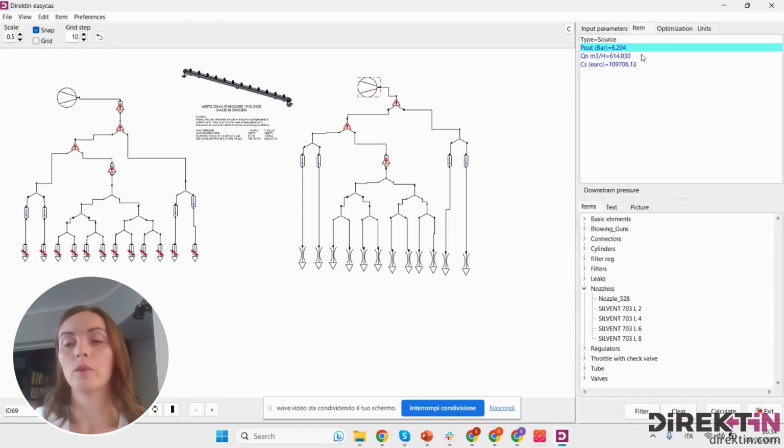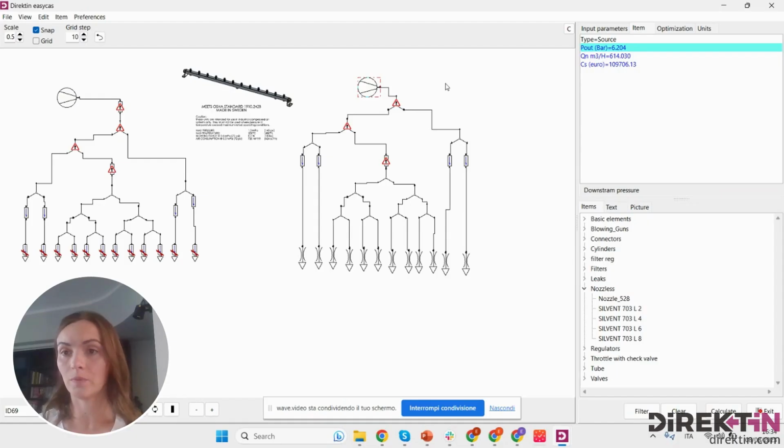4 bar or 5 bar here, because we saw in the manometer, and we also have a measurement, that the operating pressure here was about 3.5 bar, so it was way lower. So what I wanted to say here is that this model shows us that the system was not working as projected.